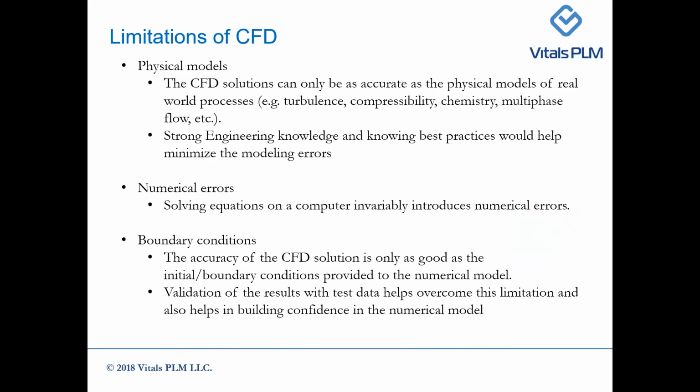Coming to the limitations, physical models. The CFD solution can only be as accurate as the physical models of real world processes. It depends on which turbulence model you choose, the compressibility, whether it's an ideal gas or real gas, the chemistry, and how you model multiphase. So it all depends on the physical model you use. And strong engineering knowledge and knowing best practices can help minimize these modeling errors.